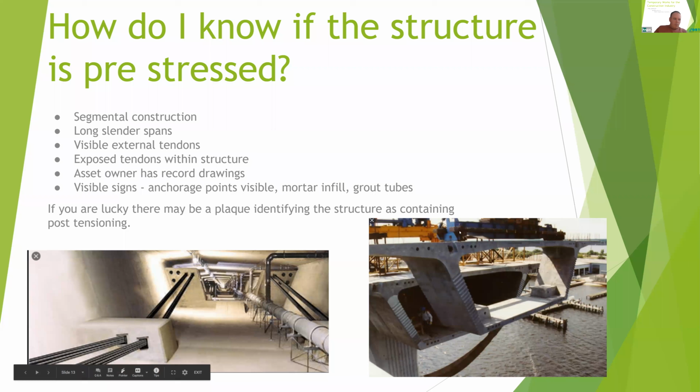So if you're coming along to demolish a structure, how do you know if the structure is pre-stressed in any way? There are some giveaways. So segmental construction, that's on large scale bridges here. Each of these is being precast and gets lifted up into place with a traveller and then is anchored to the next one with a tensioning system. So that's normally a giveaway. The structural form of a structure can often be a giveaway. If it's quite a long, slender structure, that often means there's pre-stress involved somewhere.